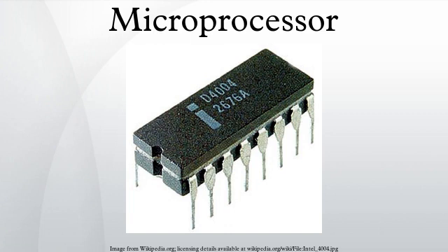AMD's G34 motherboards can support up to 4 CPUs and Intel's LGA 1567 motherboards can support up to 8 CPUs. The modern desktop sockets do not support systems with multiple CPUs, but very few applications outside of the professional market can make good use of more than 4 cores, and both Intel and AMD currently offer fast quad and 6-core desktop CPUs, so this is generally a moot point anyway.